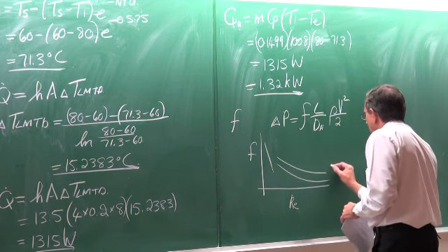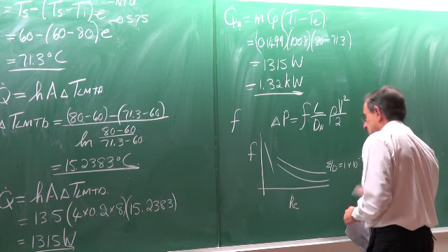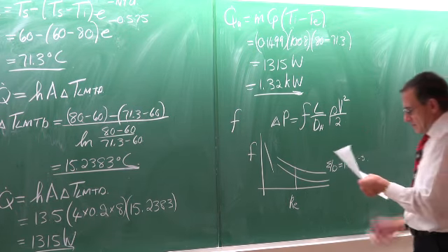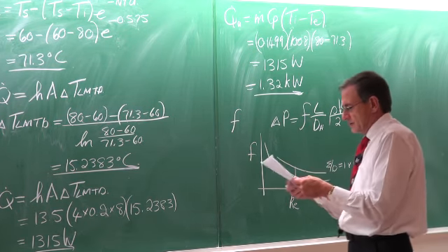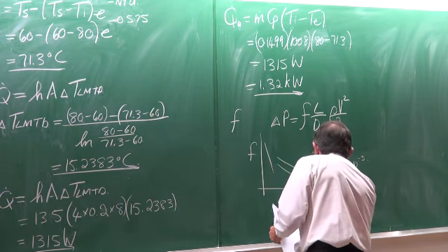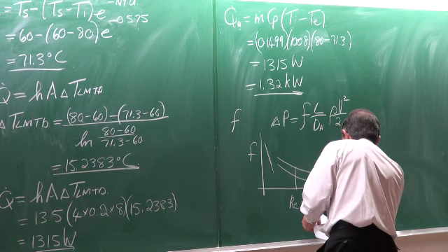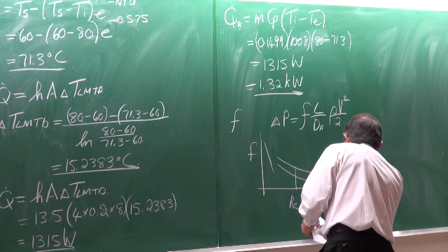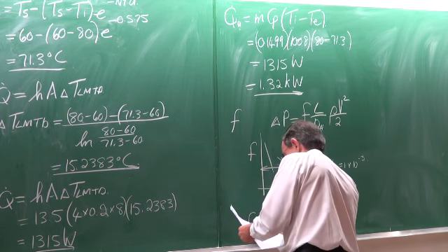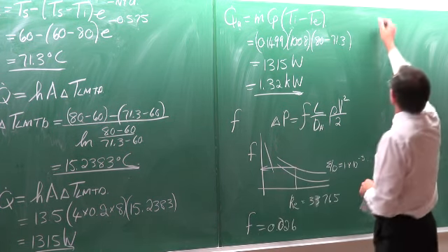And if we go and look for the line where epsilon divided by d is equal to 1 multiplied by 10 to the minus 3, and we look at this Reynolds number that we've determined, 33,765, then we can get the friction factor as 0.026. The friction factor is equal to 0.026.